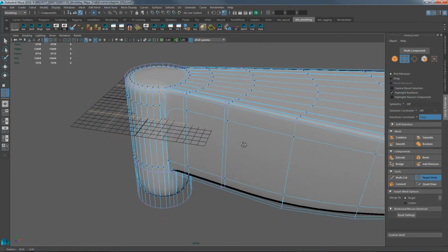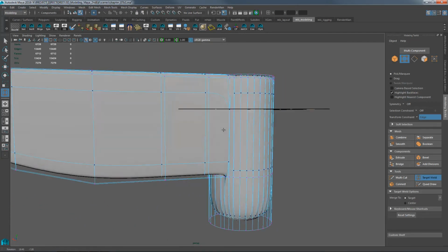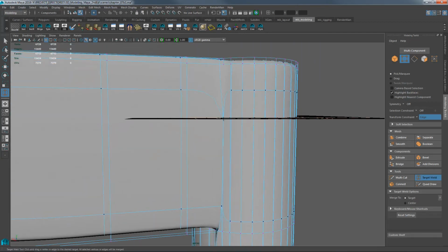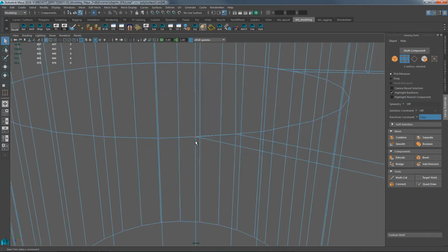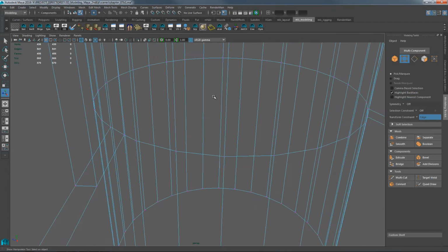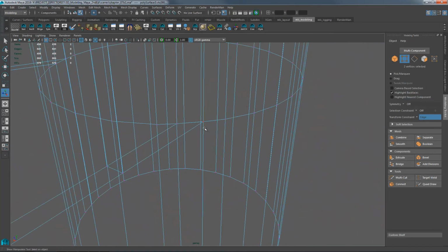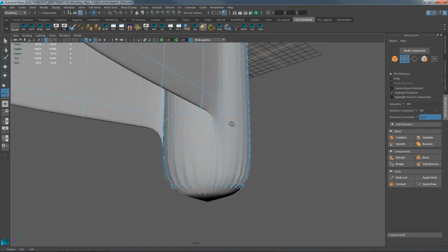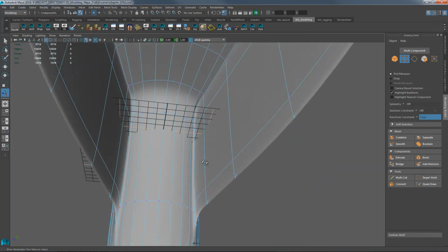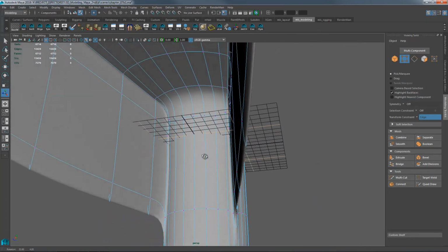I think I got everything. Oh, it looks like I still have a couple of floating ones missing. You can see these big arrows when turning on subdivision surfaces. Something's not quite right there. Yeah, selecting this one here. It looks like one, but it says there's two there. So I just selected both of them and chose merge. Just the regular merge. And probably the same thing over here. Yeah, it says two. Merge, and now I've got one. Okay, those are clean connections. Other than the crazy n-gons at the poles, these are good connections, and now I'm going to spend time adding